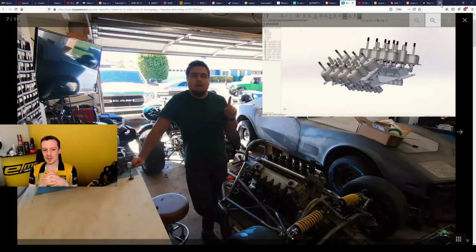Also things that you can do. But again, if you want to vary that a lot, then you need more valve area per displacement. So you might end up needing to run a larger bore-stroke ratio, which means your combustion efficiency goes down a little bit because your combustion chamber gets flatter and wider instead of more round. So there are trade-offs with that system also.